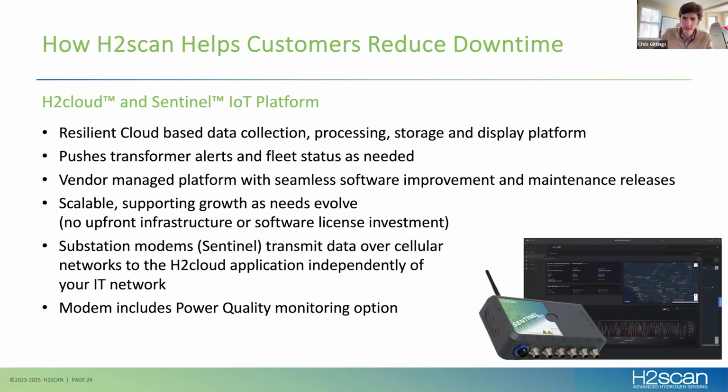Can the H2scan feed into a BACnet BMS system? This particular product that you see today does not talk BACnet. It's just pure Modbus over RS485 or DNP3. We also have a very similar product designed for environmental area monitoring in battery rooms, where gases are given off when batteries are charging, or in energy storage systems.